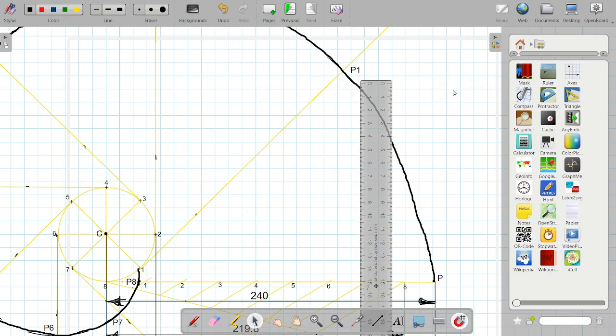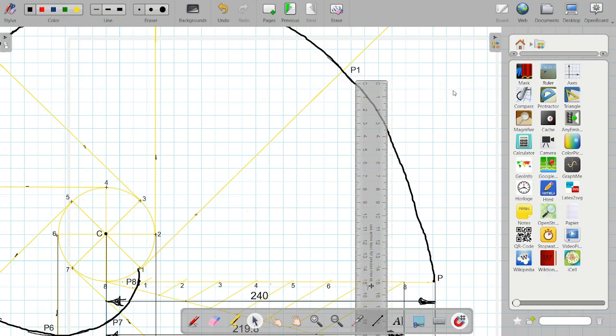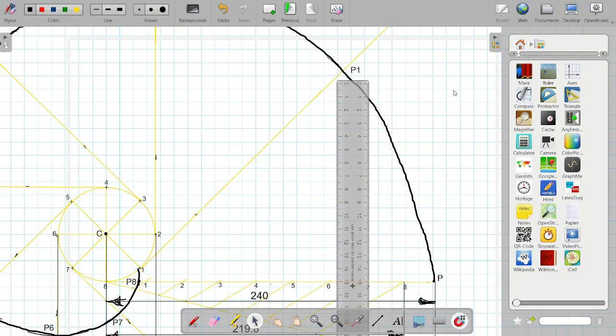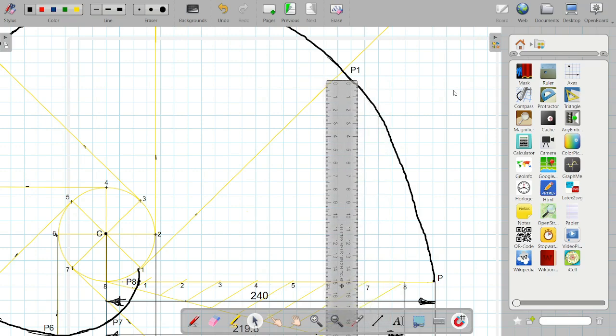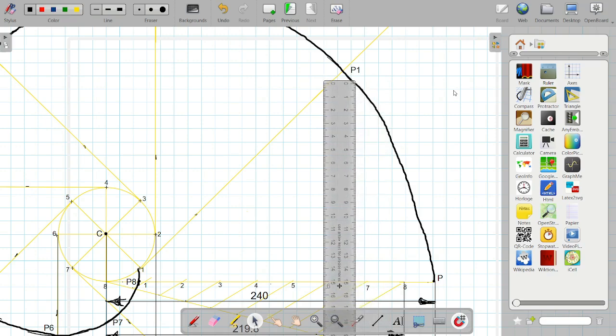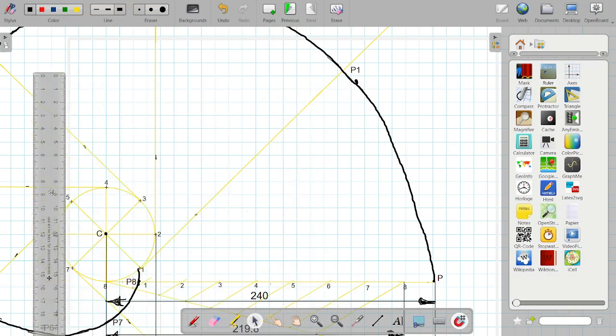So I will slide my scale this side, and wherever this 15 mark touches the curve, this is the point on which I need to draw normal and tangent, which is 150 mm above the line. So I will mark this point.